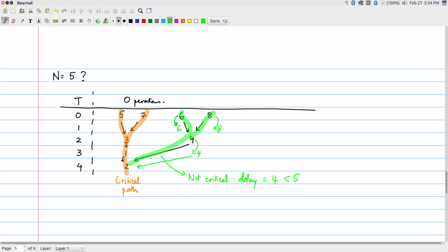Okay, I am anticipating a little bit over here. This is essentially the same as the concept of slack in a digital combinational circuit, right? There is some slack on this path, whereas on the 5312 path or the 7312 path, there is no slack. They are exactly critical. The others have slack. They have some amount of mobility. Okay, so how does this help us?